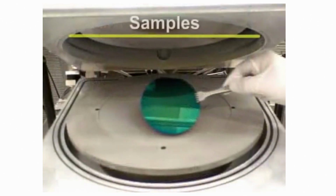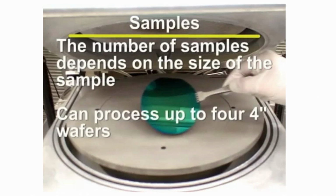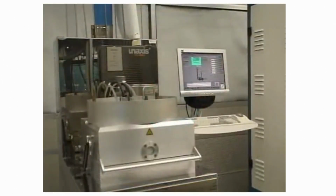The Unaxis PECVD can process a wide range of sample sizes. The number of samples depends on the size of the samples. A typical run can process up to four 4-inch wafers. Typical deposition rates range from 60 to 600 angstroms per minute. Now let's go over the various parts of the Unaxis PECVD.